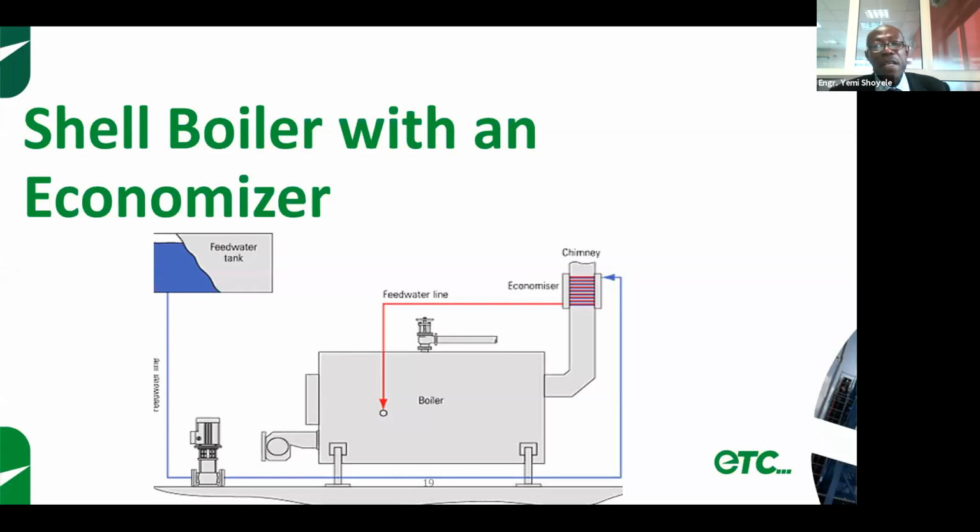That is to make sure that we can use the usable exhaust gas temperature. Okay, but care must be taken not to bring down the temperature of the gas leaving the chimney too low, as that will cause corrosion, because a lot of the oils we use have sulfur, and sulfur, when burned, becomes sulfur dioxide, and moisture with sulfur dioxide is sulfuric acid. So by design, this is nothing anybody can do about it. The operator or the user cannot do anything about it. It's already designed in such a way that you will not fall below a certain temperature.